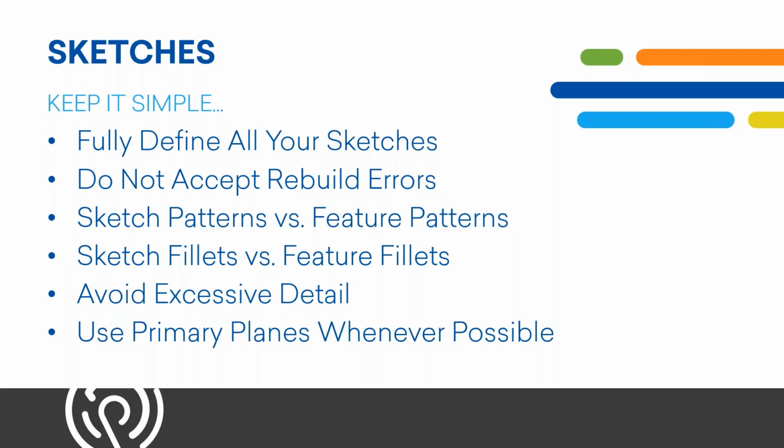So the detail inside of your sketches, you want them to be fully defined, but you don't want to strive to have every bit of detail in one sketch. That works out well for certain modeling practices. You can also reuse sketches, so that kind of defeats that, where you could use multiple features and work with what I was just talking about there with suppressing or simplifying. But if you're not used to that, then I wouldn't worry about that for now. We can teach you how to use one sketch multiple ways.